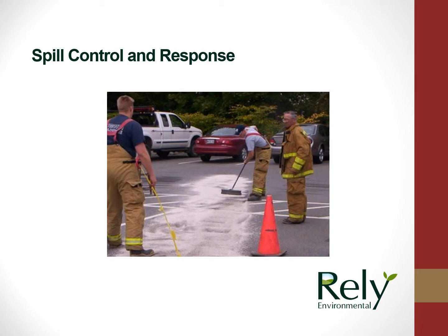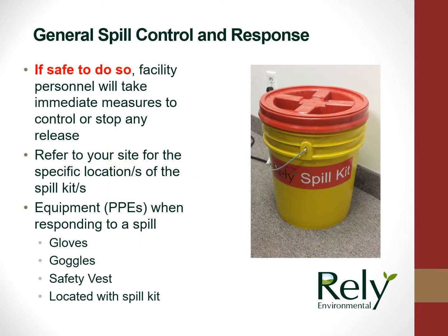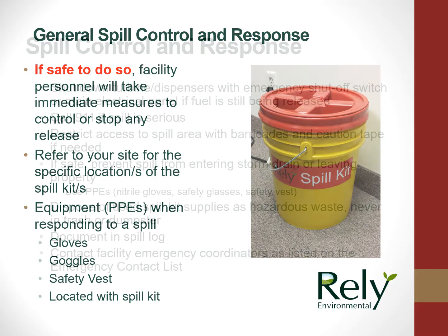We will now move on to spill control and response. General spill control and response. If safe to do so, facility personnel will take immediate measures to control or stop any release. Refer to your site for the specific locations of the spill kits. Remember to use personal protective equipment or PPEs when responding to a spill. These include gloves, goggles, and safety vests. PPE should be located with the spill kits.